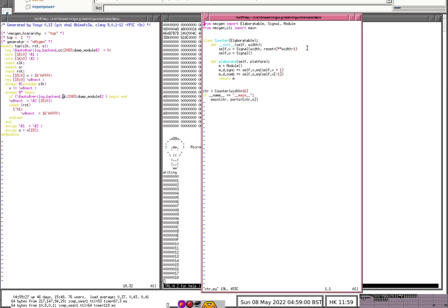Right now, self.v equals reset to the power width minus 1, so that's FFFF. Look, a reg v got created at 16 bits with a 16-bit constant, starting off at FFFF. Hooray! v$next means the next version of v, which is due to the sync domain here.